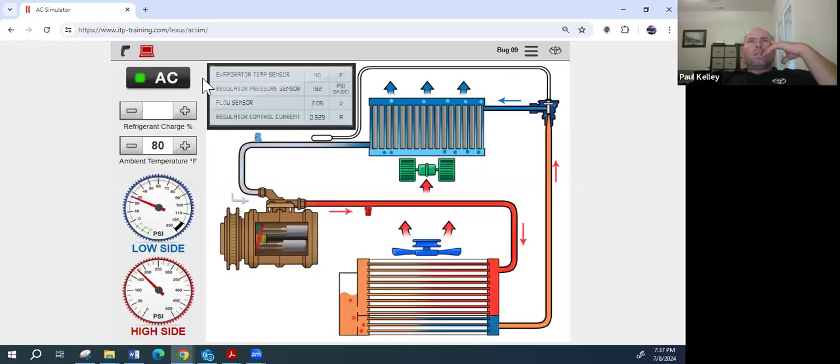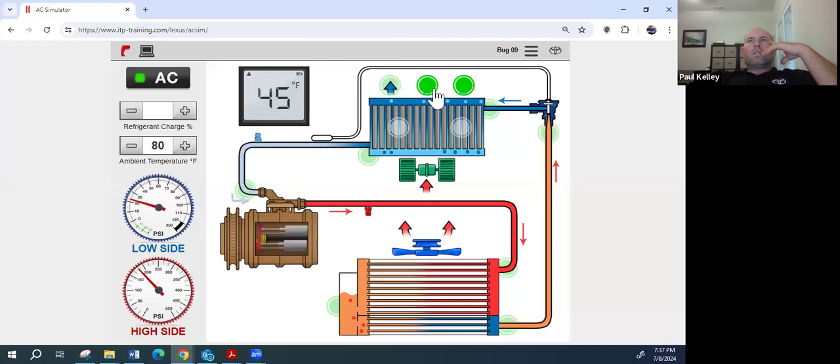Jump in the car, turn the AC on, check it. Blowing 45, that's all you could ask for, really, because that's the thing, it's humid there. The AC doesn't work as well when it's humid. 45 on an 80-degree day would not be great for Southern California. But 45 in high humidity on 80 degrees, I don't know if I really object. But what was the concern again? Oh, sometimes. Now it's blowing 70. 78, 79. No, that sucks.